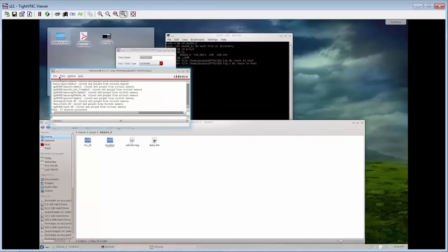Otherwise, if you try to open Cadence on another computer after you log off, it won't let you open the previous files because all files will be locked. So it is always a good idea to click Close Data, select all, and then close. Now we can exit.